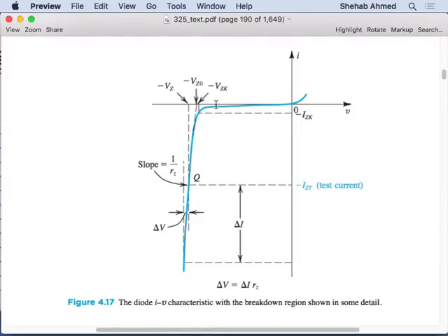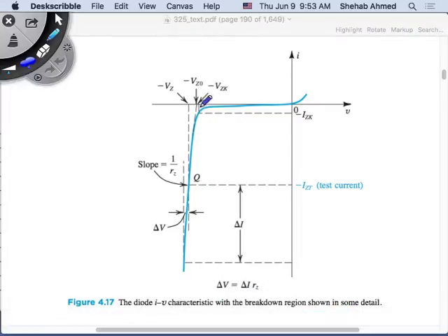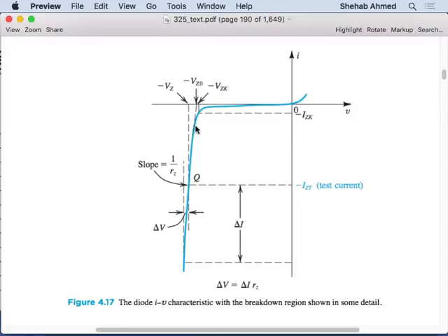At some point, VZ0 becomes what? If you're operating here, where is the slope? It's going to intersect very far away, so you're not going to be regulating anymore. That's what's happening. You're moving up, VZ0 is changing, and what's happening also? The current is decreasing. So your VZ0 is decreasing, and your I times R is also decreasing. At some point, you're very far away from VZ, which is your regulating voltage requirement, and you're out. You're no longer regulating it, okay?